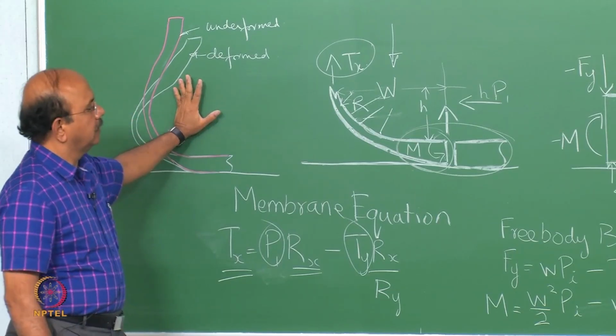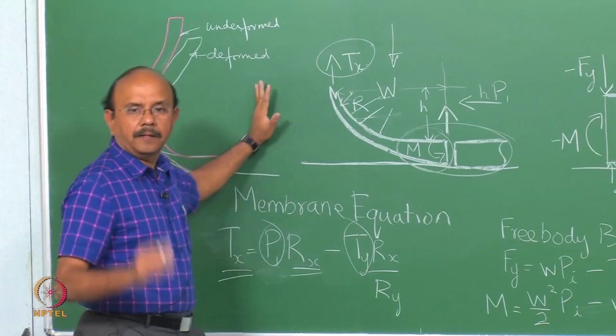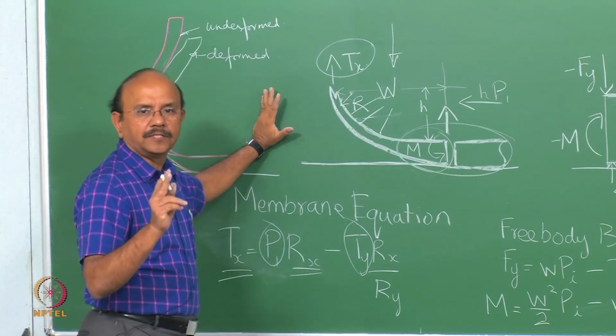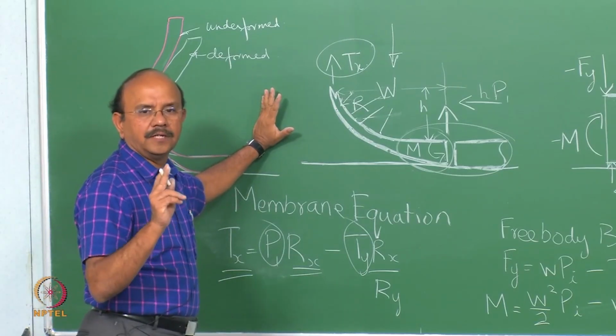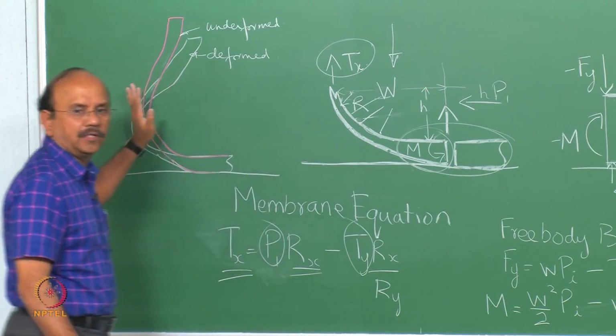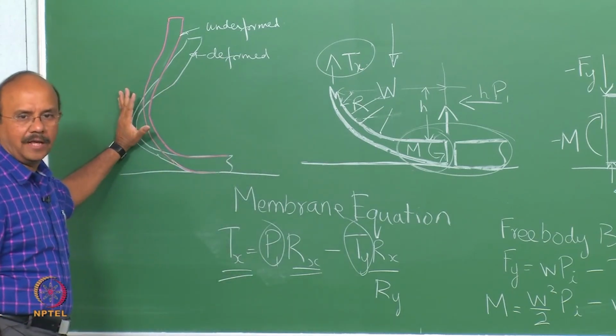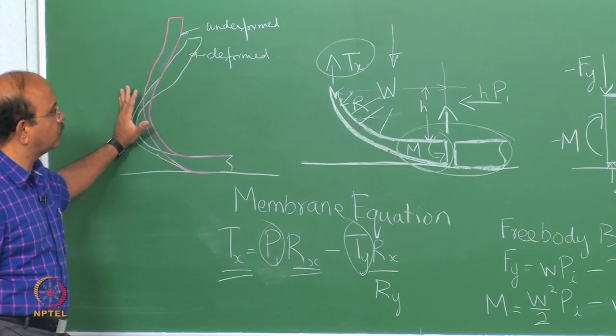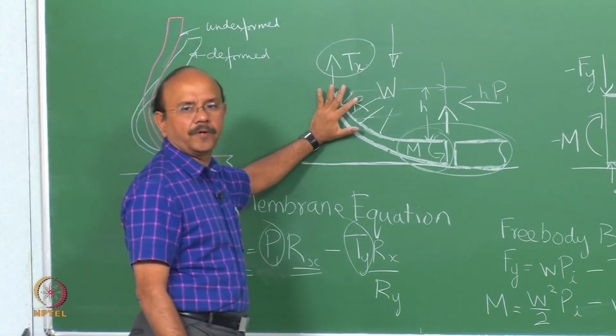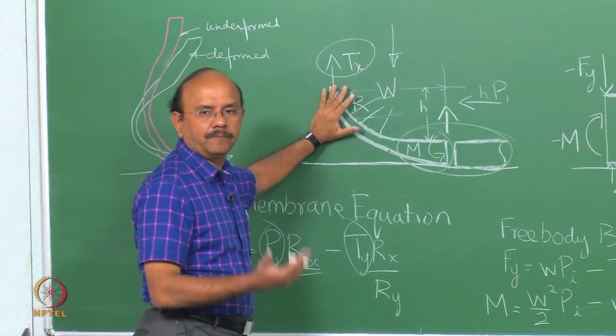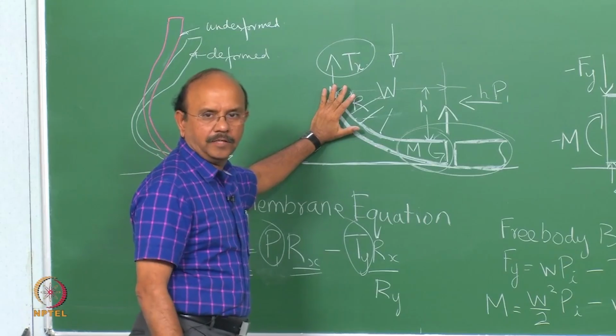That's the first thing. The only thing I want to point out is that this force is affected by the shape or the profile of the sidewall, as well as the inflation pressure to which you subject the tire. These are the two things.